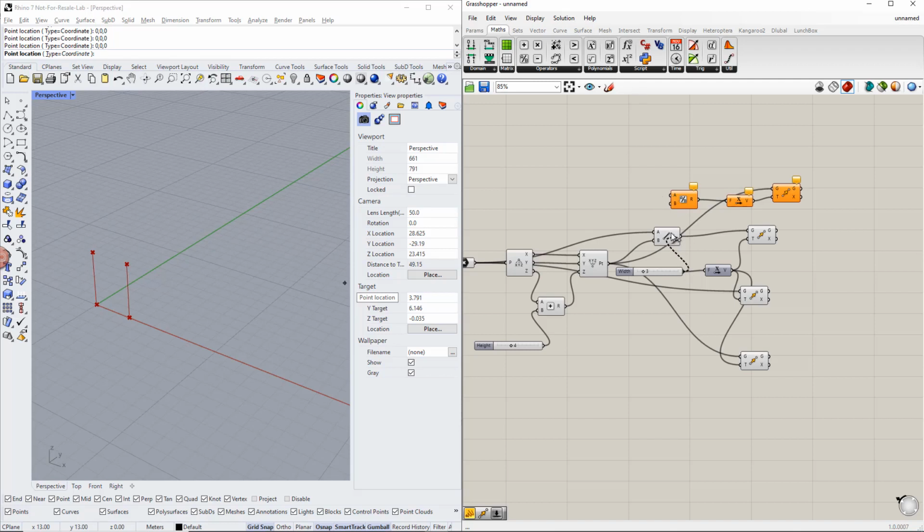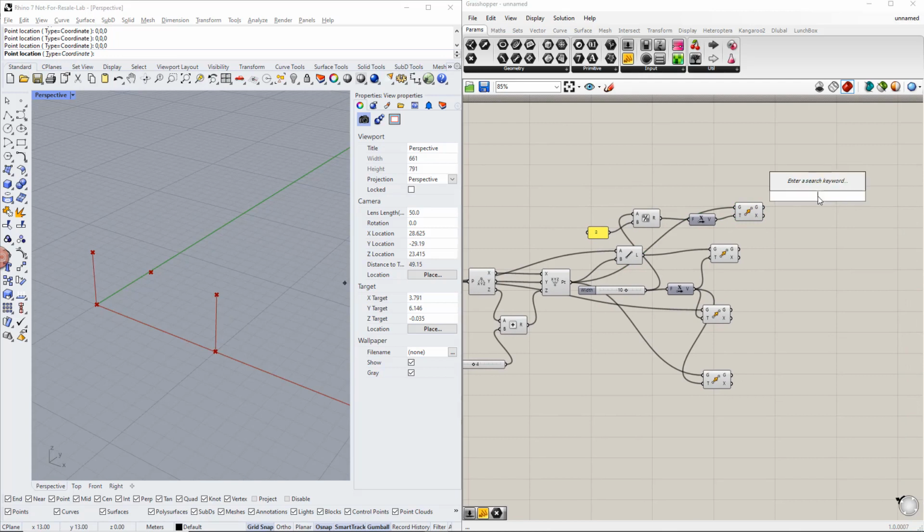The first value, a, is the width value. The second value, b, is 2. We can enter it using the panel command. Afterwards, we copy this point in the z direction using the move component. We also need to insert the unit vector parallel to the z-axis component.